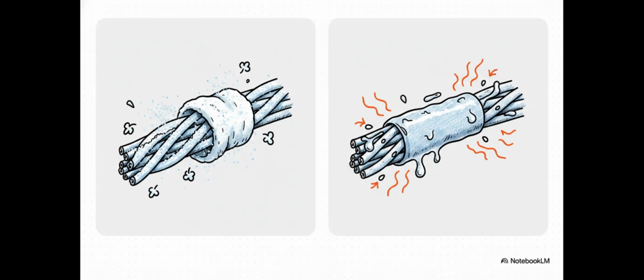High flex can usually just rely on standard talcum powder, chalk, or maybe a thin fleece wrap for its occasional bending. But continuous flex? It requires specialized heavy-duty lubricants, low-friction fleece, or even extruded inner jackets. It literally needs these robust materials just to survive the massive internal friction and heat generated by non-stop operations.